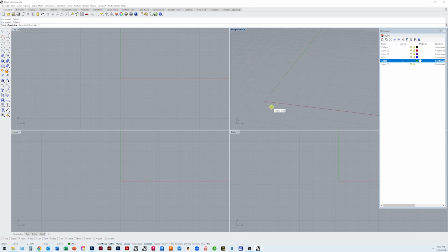So let's make a polyline, and you made these. You guys are all very familiar with them because you just spent the last 2 weeks drawing two-dimensional patterns. So I'm just going to draw a box with those. So that's using a polyline to draw a box. I could also have gone in here to the rectangle tool, and I could have drawn a box like that. Okay. So once I have a box, I can click on that curve.